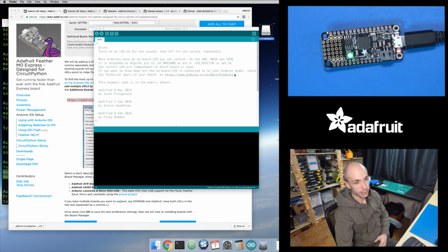And then the cool thing is this bootloader supports both the old mode of using the BOSSA tool, which is what Arduino uses internally, or the drag and drop Feather boot drive method. So you can use either method, it's fine. You don't have to do anything special. You just double tap the reset and it's waiting for either BOSSA or the drive .uf2 file. So Arduino doesn't use the UF2 file stuff, but it uses that BOSSA tool internally.